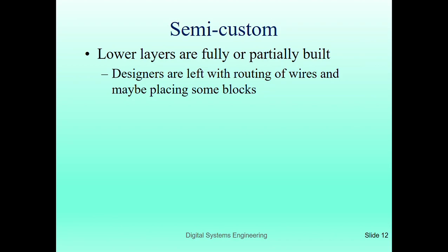Semi-custom IC design is a methodology for making an integrated circuit in which a portion of circuit function is predefined and unalterable, while another portion can be configured to meet designers' specific needs. So the designers have the capability of designing application-specific circuits themselves using either standard cell libraries or pre-configured arrays.